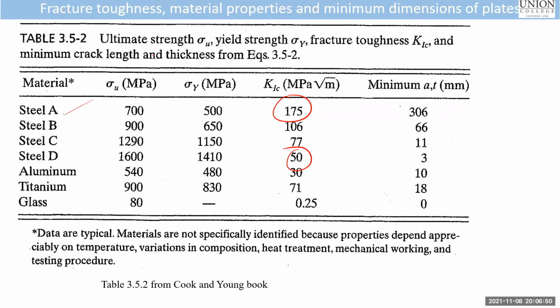I have some examples here. For the first mode, K1C under tensile loading, steel can take only 175 megapascal root meter. Those are the units, and the root meter in the units should make sense to you. K1 is beta sigma root pi a, right? Beta is just dimensionless. Sigma has the units of megapascal, and if the crack length is in meters, the units are megapascal square root of meters. And steel can have a maximum value of 175 before it can't take any more.